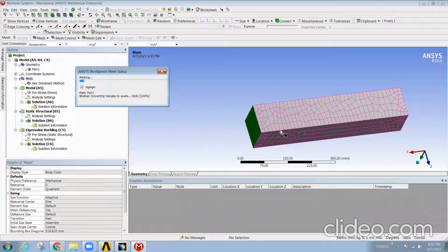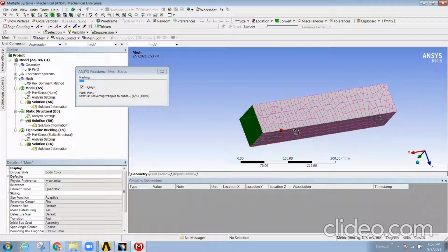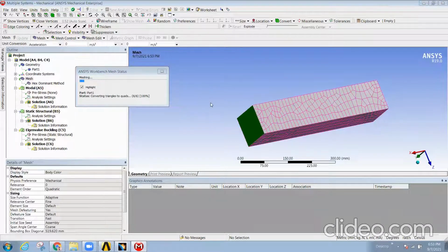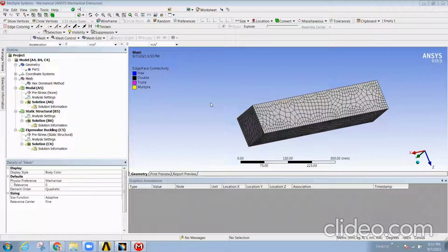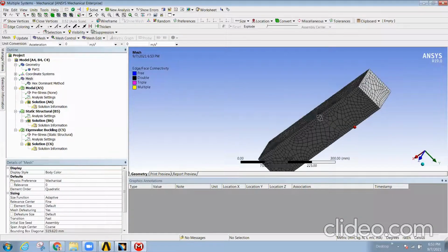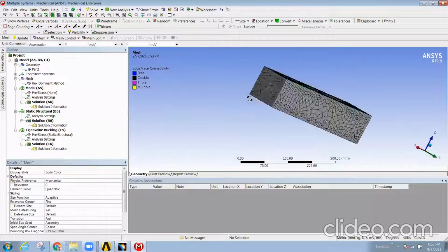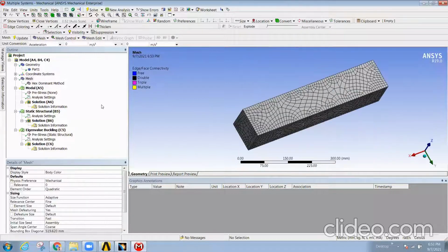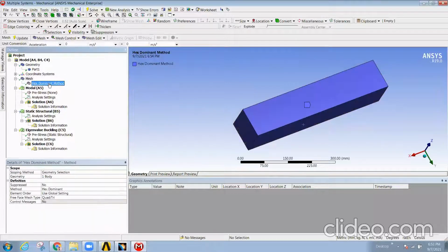Fine in the sense the mesh will go too fine, so the number of elements and the number of nodes will be increased, which makes your geometry more complex to solve, or rather, more nodes are increased. As here you can change this to only hex or all quad on the 2D faces.